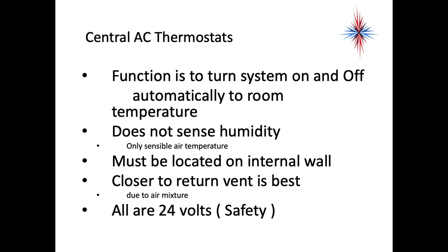And it does it automatically, and it adjusts it to room temperature. A basic thermostat does not sense humidity. It only senses sensible temperature. Now let's go back and remember, sensible temperature is temperature I can measure. Latent temperature, which is basically part of humidity, is temperature I can't measure, but is heat or lack of heat, heat addition and heat removal, having to do with the change of state, like from water to humidity.